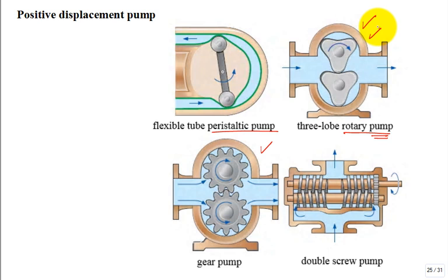And so that's why they have those type of pumps. It's going to have a flow rate linked up to the RPM, yes, but it's going to be very controlled. Here's a gear pump, and then here's another one where you have a double screw. So they're always trapping and then pushing through a particular volume.